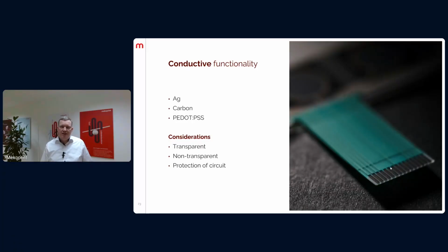So the type of dielectric ink that we can choose can be dependent on what properties you require, such as do you need a high amount of breakdown voltage, do you need very good bending properties, or do you focus on decreasing yellowing of the ink? We also have other options to, for example, laminate a protective foil instead of printing it, or we can do both.